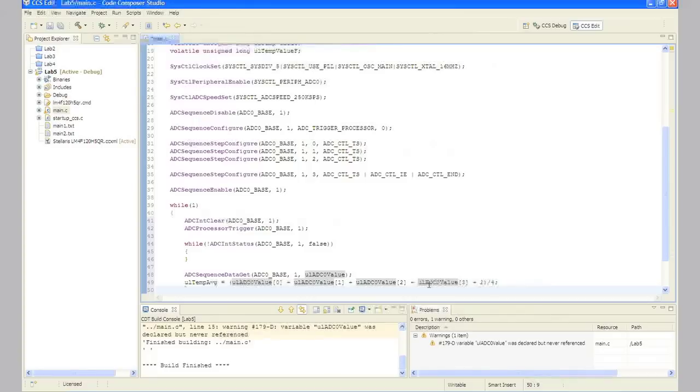In step 22, now that we have the averaged reading from the temperature sensor, we can calculate the Celsius value of the temperature. The equation below in the workbook is shown in section 13.3.6 of the LM4F120H5QR datasheet. Division is performed last to avoid truncation due to integer math rules. A later lab is going to cover floating point operations.